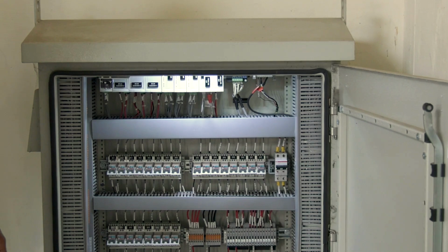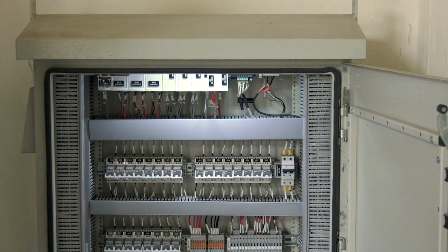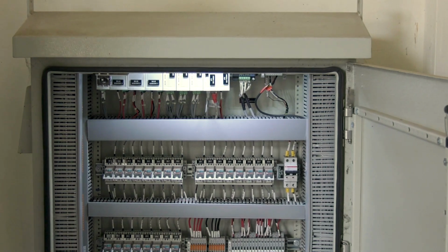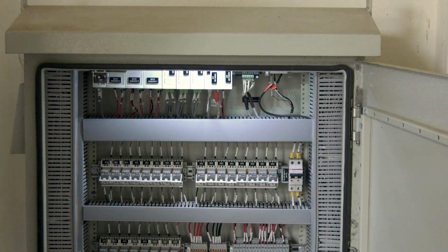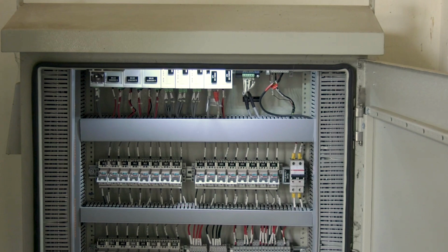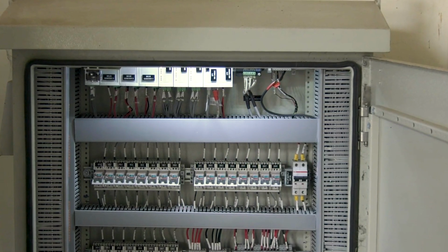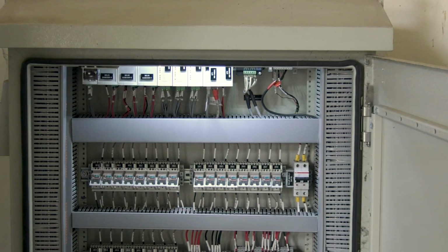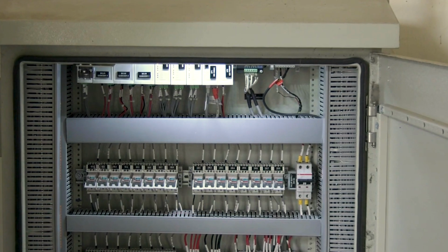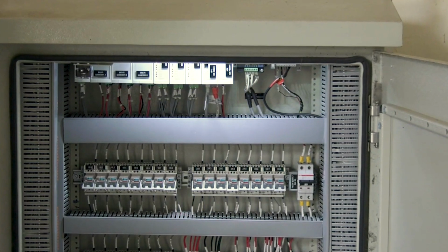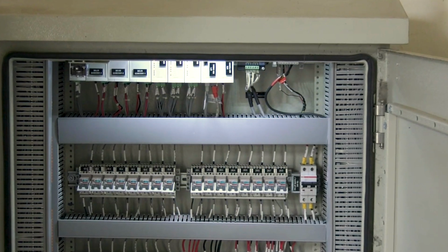Now, let us explore the feeder remote terminal unit, a critical component for monitoring substation equipment and real-time data acquisition from all incoming and outgoing feeders. The FRTU captures status signals of devices and performs automatic data logging, thereby enabling substation level control. In the top section, we find the communication modules and controllers which facilitate real-time data exchange with the central control system known as SCADA, thus enhancing the reliability and automation of the electrical network.